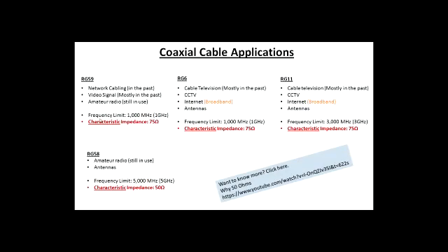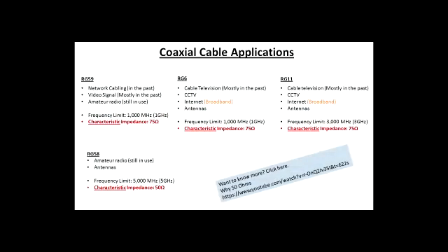Okay. The frequency limit, the bandwidth. What I mean by that is how high of a frequency signal you can send on one end, and the cable is going to handle that, keep the integrity of the signal that is understood by whatever the equipment on the other end. How high frequency can you pass through that cable when it comes to analog signal, which is basically radio signal, radio frequencies in megahertz or in kilohertz. Right? So the frequency limit of RG59 is,